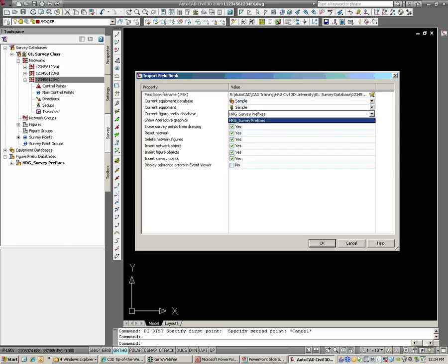See where it says this survey, HRG survey prefix library? You need to make sure that that is set current. That's a part of these settings when I was saying the whole dialog here. Take a look at it. That is what tells the points to be on what layer and what line work to draw in. So that's a good point. Make sure to check that as well.